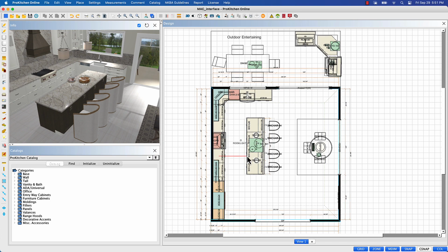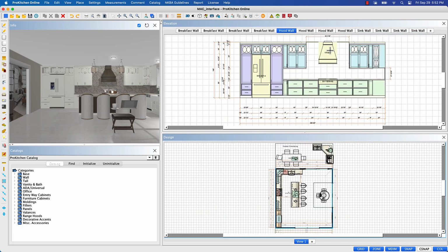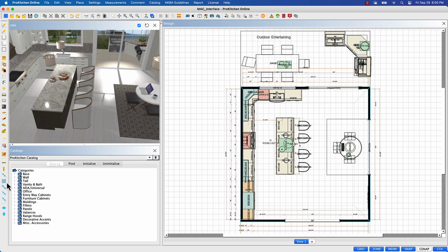The Measurement section holds standard measurement tools for horizontal and vertical measuring. The blue arrow tools are both dynamic and static dimension tools. Point-to-point, point-to-line, and line-to-line are all dynamic dimension tools, while the angular and multi-dimension tools are static. It's important to remember that when using the dynamic dimension tools, you must select the stationary item or line first, as the last item or line selected is the one that will move.